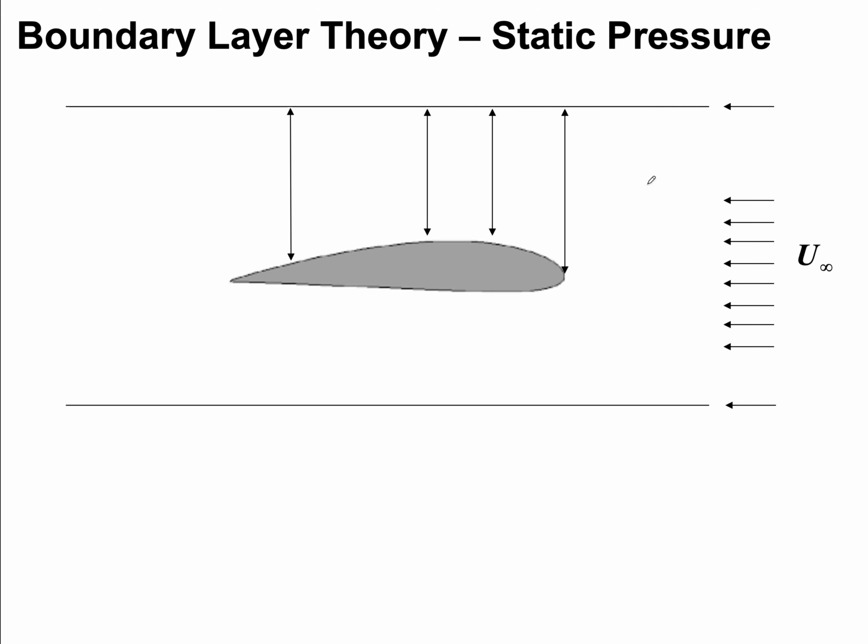So if I have the same mass flow rate going through, these are the three areas, A1, A2, and A3, and the area A2 is smaller than A3 and smaller than A1. So I get a decrease in area and then an increase in area. And if you remember, the mass flow rate per unit density, or divided by density, is the velocity of the flow multiplied by the area.